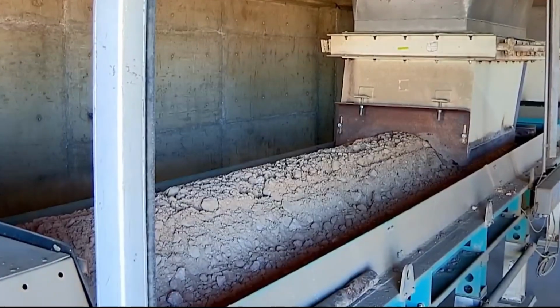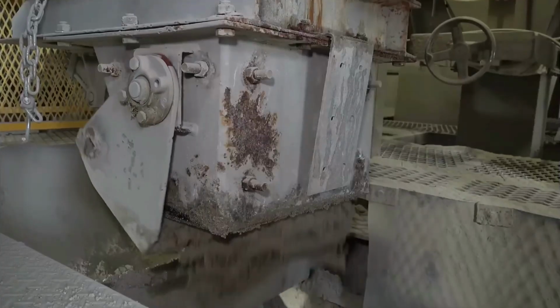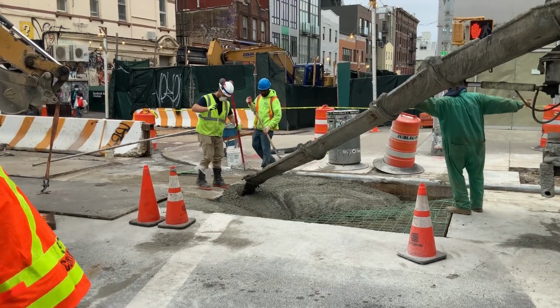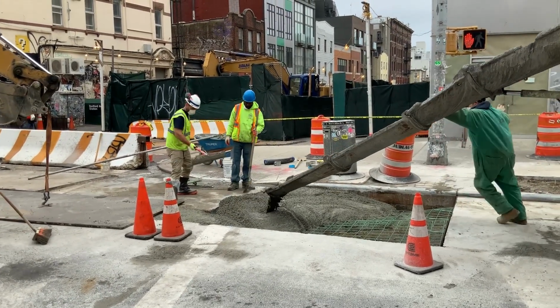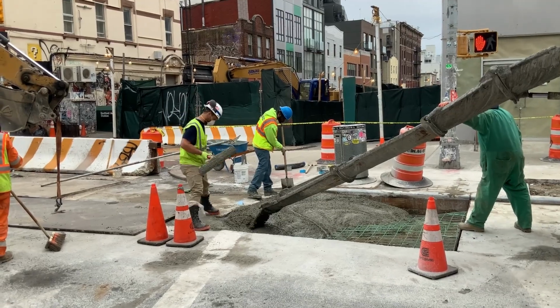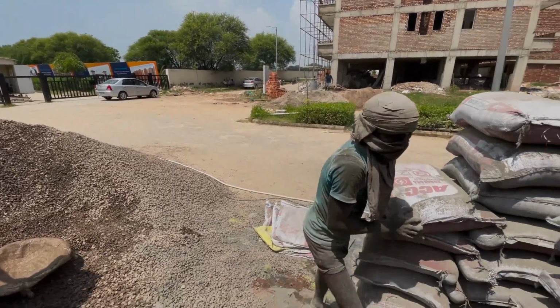The clinkers are then finely ground and mixed with gypsum, and often with alternative raw materials to make cement. The grinding process enhances the cement's reactivity, ensuring optimal performance in various applications. Gypsum is added to cement to control its setting.